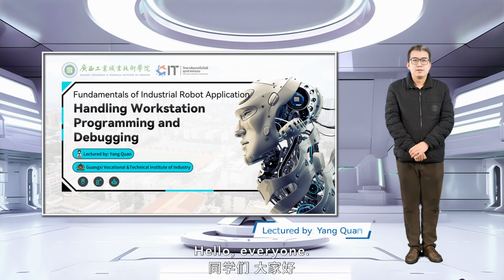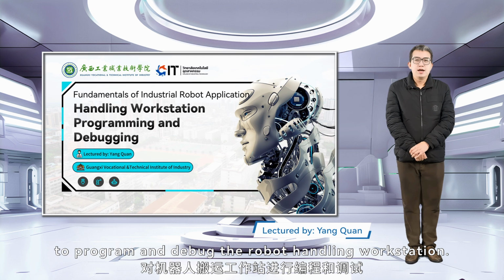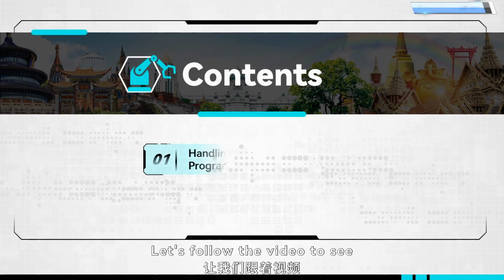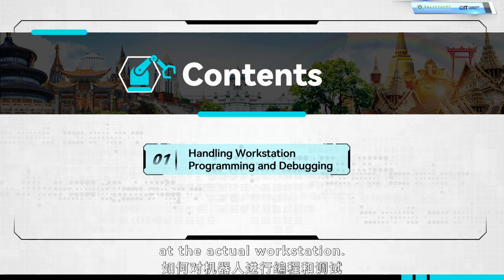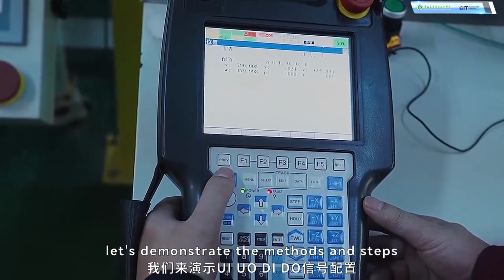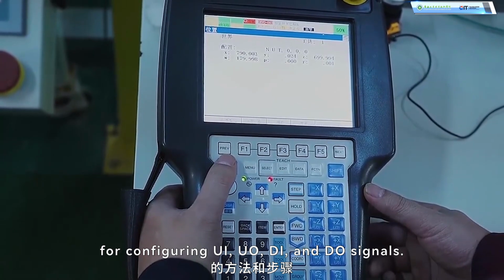Hello, everyone. In this lesson, we will build on the foundation of the previous lesson to program and debug the robot handling workstation. Let's follow the video to see how to program and debug the robot at the actual workstation. Before programming, let's demonstrate the methods and steps for configuring UI, UO, DI, and DO signals.